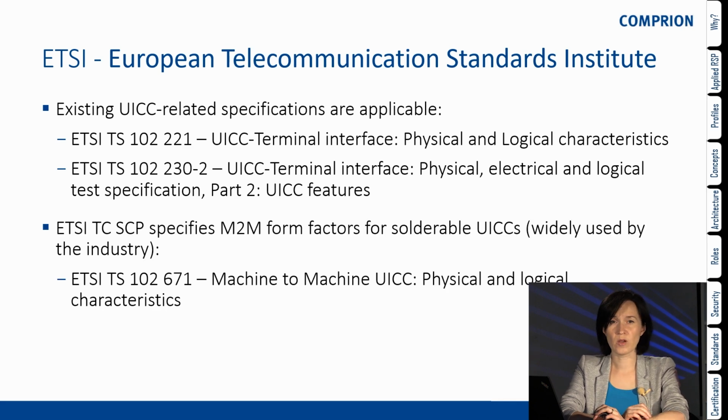And then coming closer to the definition of the EUICC, we have the form factors for M2M specified for solderable UICCs. These are the famous MFF1 and MFF2 form factors. So you know all of the formats we have right now, and this is also one of them. This is the specification ETSI TS 102 671, machine-to-machine UICC, physical and logical characteristics.